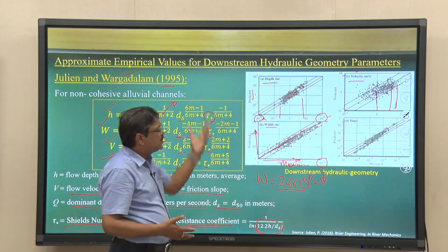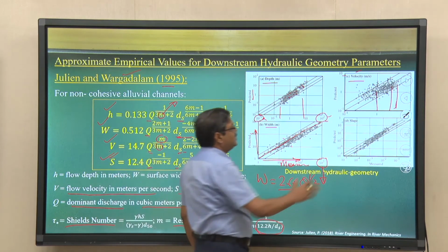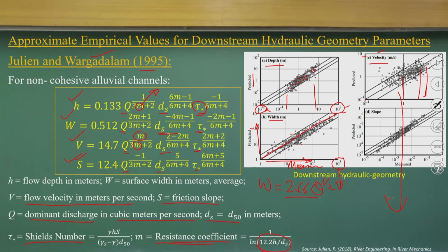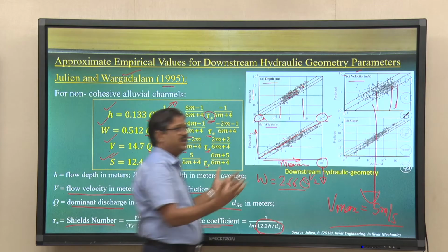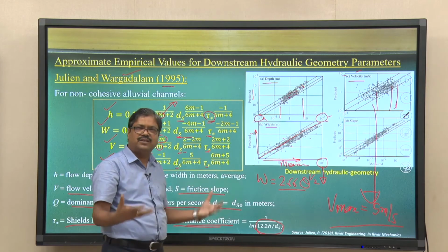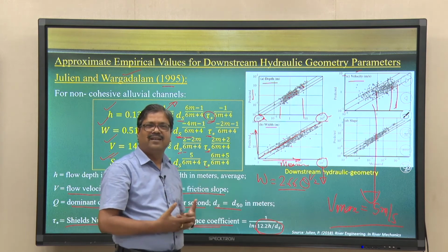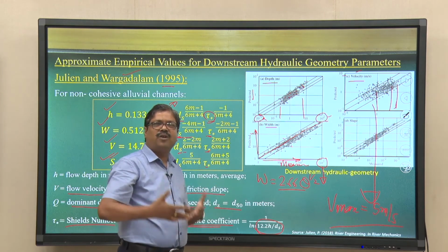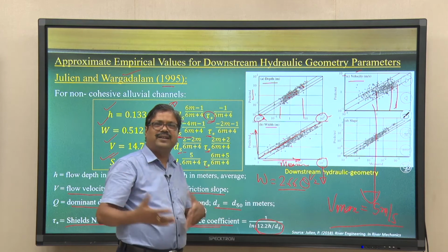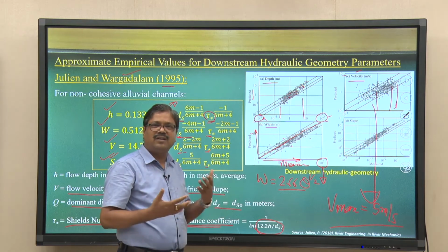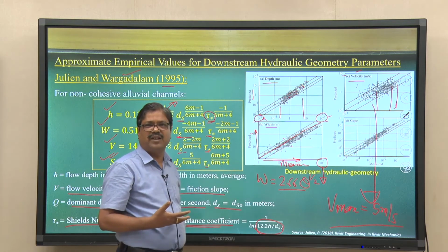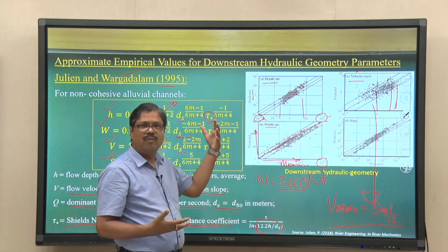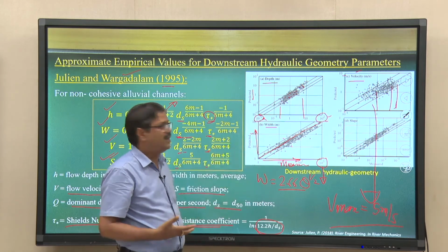When we interpret this data, we can consider from this measured data roughly 5 meters per second, because we design for streams, because many times in river systems we do not have the data, and we cannot wait another 30 years to collect the data and measure the velocity, but we can interpret knowledge about rivers from elsewhere as regional studies.